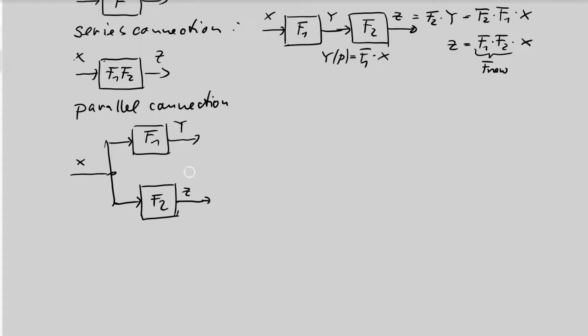For example, if this is 1 ampere and this is 2 ampere, if I connect them, how large is then the total value? That is not possible. If this is a battery of 12 volt and this is a battery of 24 volt, and I make a short circuit cable between both, then you will see there will be a very high current, and normally batteries will be destroyed. So it is not allowed to directly connect two outputs with a junction point.